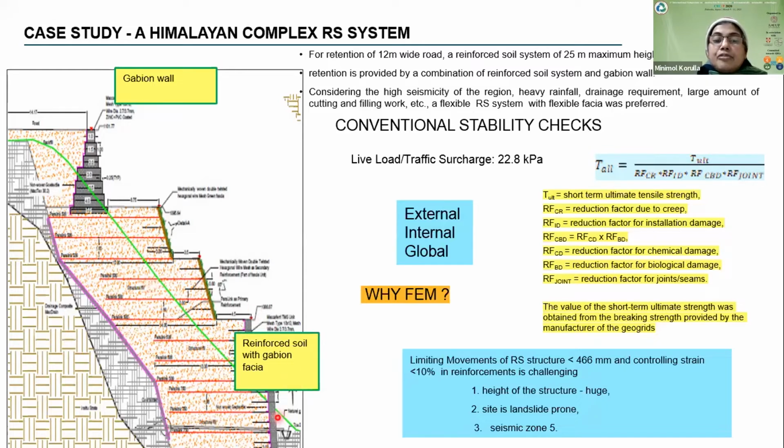Then the fascia: the lower blocks have the gabion fascia, and the upper blocks have the vegetated fascia. Both gabion fascia and the vegetated fascia are made of woven steel wire mesh elements, which have some elongation and some strain absorbing characteristics.